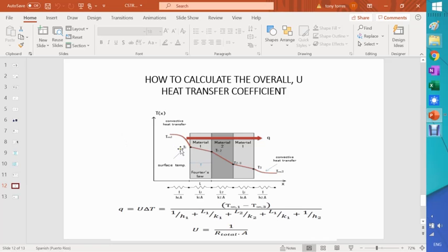So let's say that I'm going to cool my reactor. This temperature here is inside the reactor, and this temperature is at the jacket side. All right. So basically, you have a convective heat transfer coefficient that drops the temperature to the temperature at the wall. Then there's conductivity at the wall.